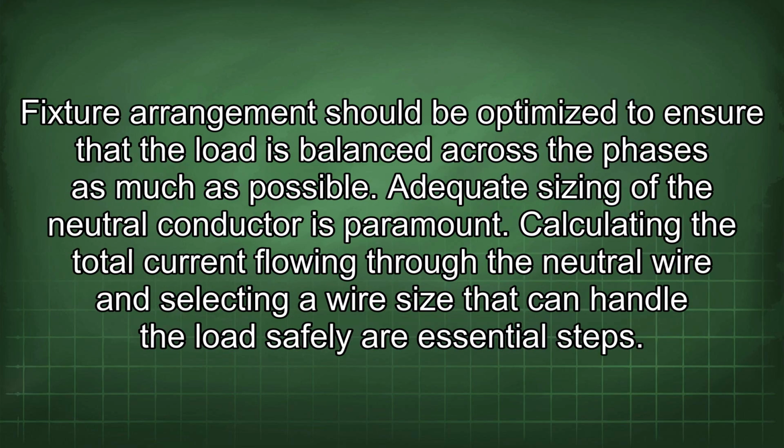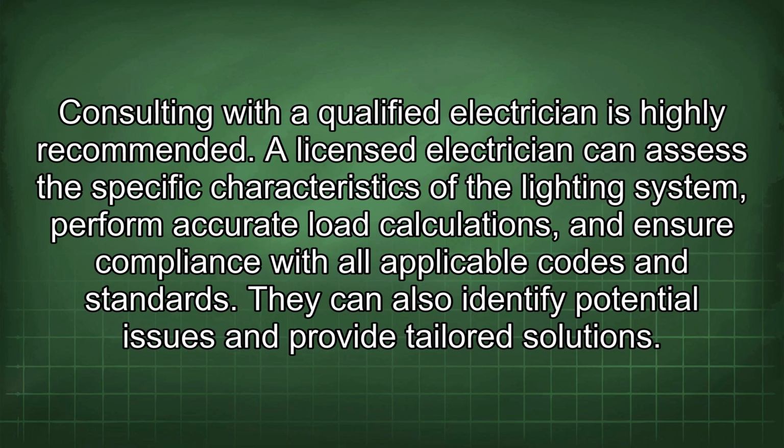Fixture arrangement should be optimized to ensure that the load is balanced across the phases as much as possible. Adequate sizing of the neutral conductor is paramount. Calculating the total current flowing through the neutral wire and selecting a wire size that can handle the load safely are essential steps. Consulting with a qualified electrician is highly recommended.